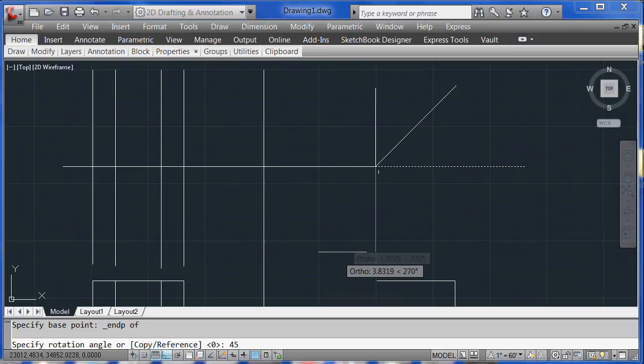So what I just did was I projected out the width of this piece here in this view out to my top view, okay? So now this is now 3.5. So this is a geometric way to construct the width, but if I would have just used the AutoCAD offset command, I would have gotten it for us as well. Okay, now we have that, and I'm going to trim up my lines here. I think these are independent now. Yep, they are.